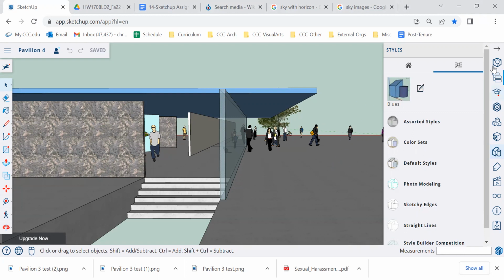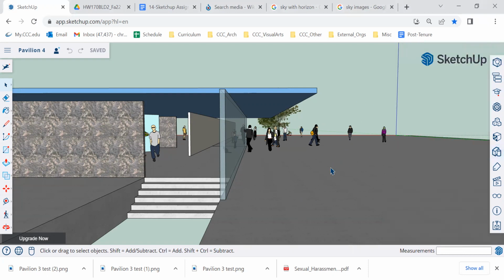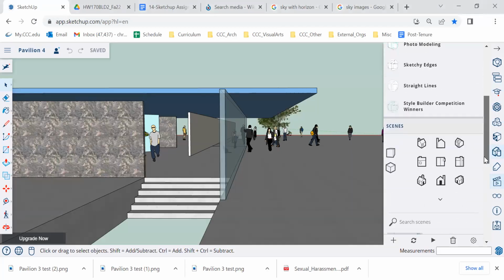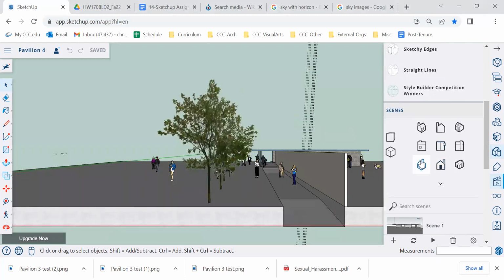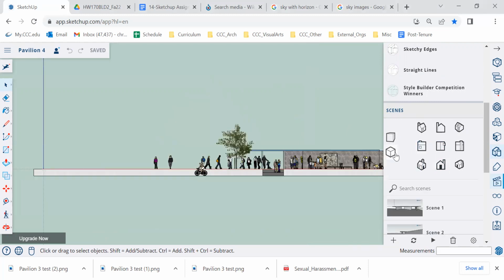One of the first things that we're going to need to do is check where we are in terms of the horizon. What do I mean by that? Well, I'm going to go to, let's see, the south elevation. And I'm going to set it to be a parallel projection because right now it's defaulting to a perspective view of the elevation. So with the parallel view, I'm going to get a more true elevation.